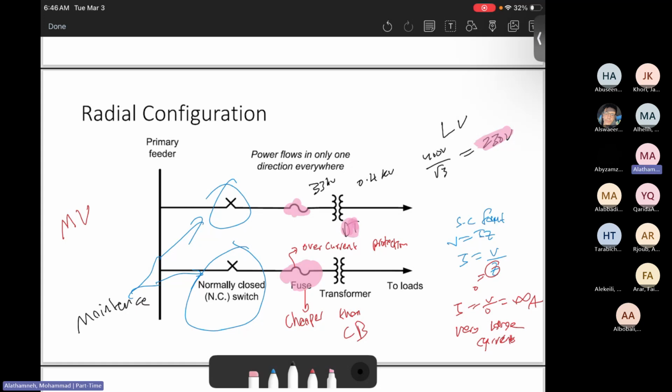So keep in mind, these switches will not be turned off if there is a fault. If there is a fault, if there's something wrong, the fuse will take care of it. But if we need to disconnect the power manually, for an extension, some maintenance, or some other arrangements, then we can disconnect it using these switches.